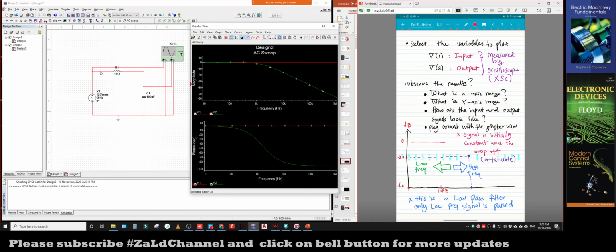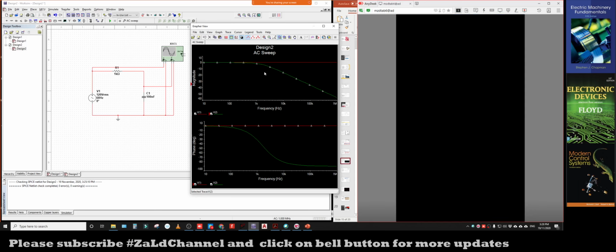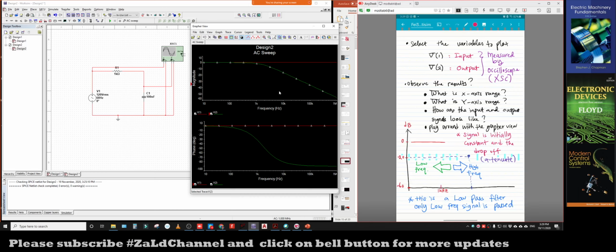At the input there is no change. In terms of the RC circuit, basically we want to see the filter effect. For example, we have this sort of signal and we want to block some frequencies. In this case, frequencies above 1 kilohertz will be blocked, filtered by this capacitor. So we will not allow signals over 1 kilohertz. This is the function of the RC filter. This is a low pass filter, meaning that we only allow lower frequency signals, and the higher frequency signals we will block.